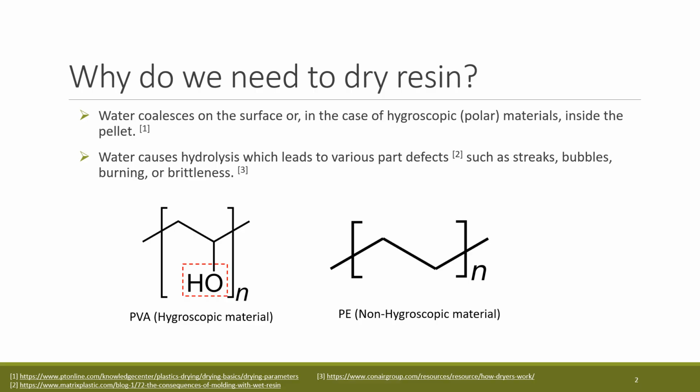Below we have polyvinyl alcohol, a hygroscopic material due to this oxygen atom creating a strong dipole moment along this bond. Next to it we have polyethylene, which does not have a strong dipole moment, and as such is a non-hygroscopic material.